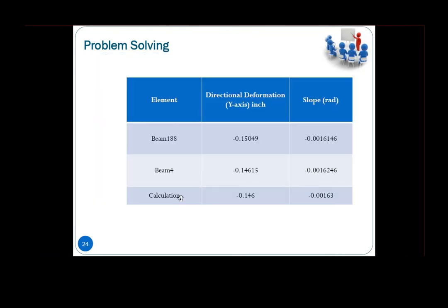You can find out that compared to our original calculations, which are 0.15 and 0.10016, the deformations or deflections in the y-axis using the original beam models, here we are talking about BEAM188 models in ANSYS, is slightly larger. Here it is because it is using different models from what we have calculated manually. So this is using a Timoshenko beam model.